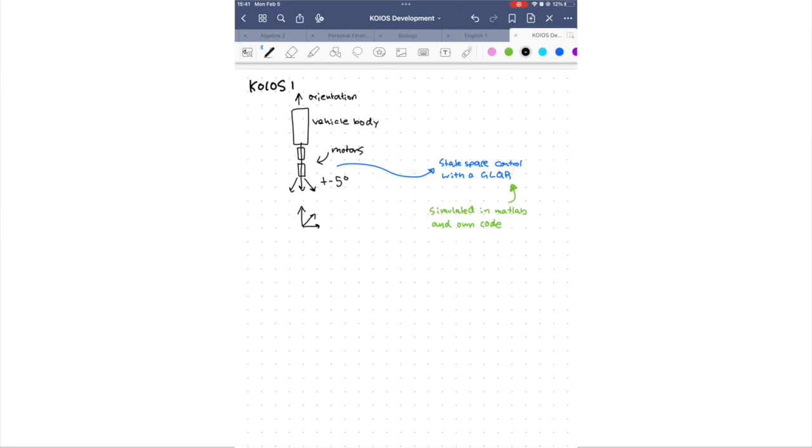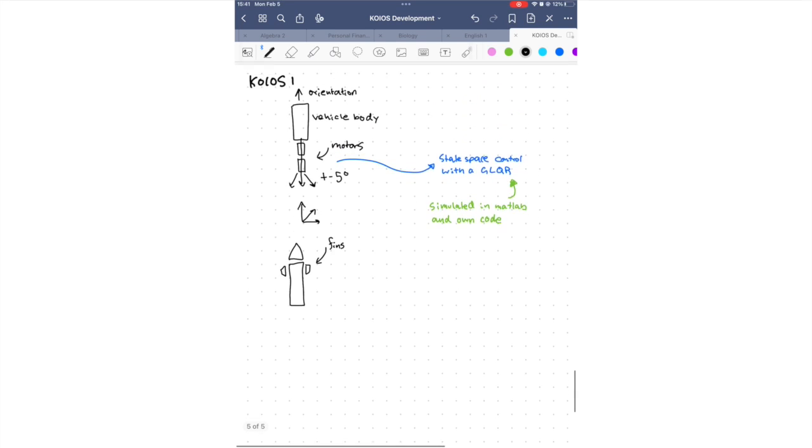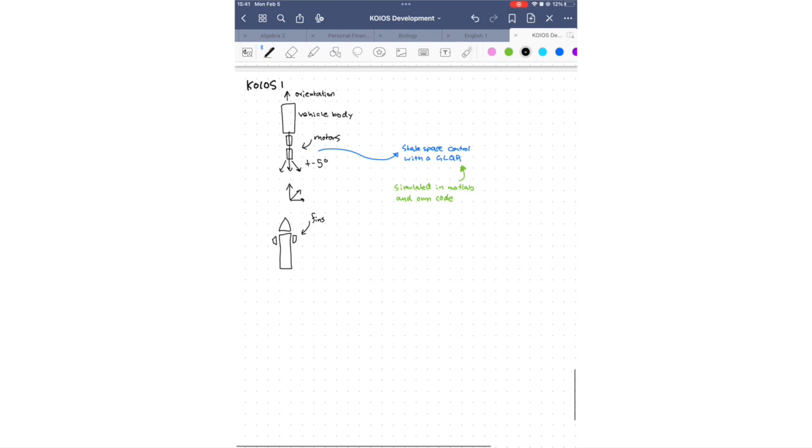But for the first system, it is quite simple. For the first descent system, it is a parachute system, which uses a black powder piston system to push out a parachute that ultimately deploys and controls the vehicle down. I have a custom printed circuit board controlled by a Teensy 4.1. This is the brain of the entire operation. I have a radio on board that communicates to a ground station.